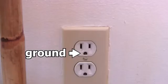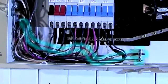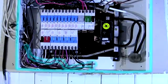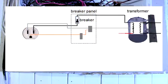So where does the ground hole go? It also has a wire that goes to the breaker panel and connects to this other metal bar, which is connected to the breaker panel's metal case. And it's not clear with this panel, but somewhere the case is connected to the neutral bar. Our diagram now looks like this, with the ground wire going to a ground bar and then onto the neutral bar. But why is the ground wire connected to the neutral bar like that?